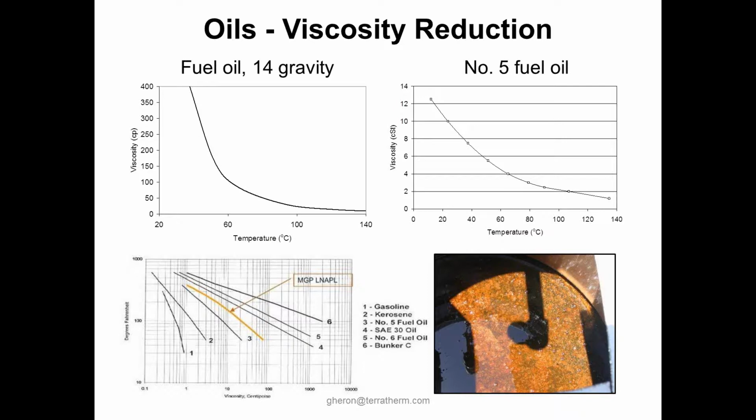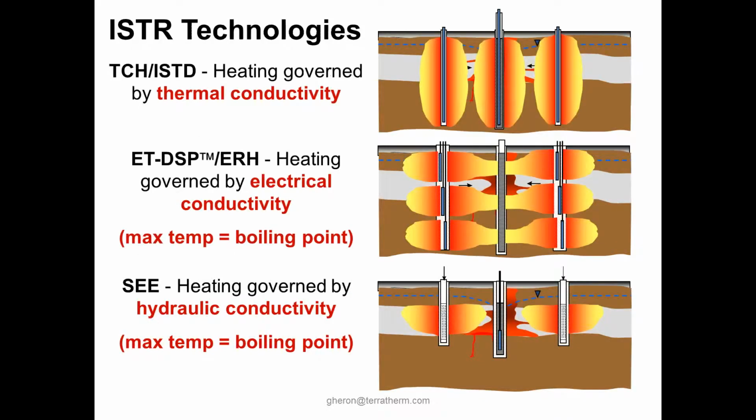But even heavy coal tar, for instance, can start to become relatively low viscosity when it gets hot. And what happens is you do extraction from sites that never really yielded any mass in the NAPL phase, and you start seeing it accumulate in your oil water separator, as you see on the right there. So you can basically start removing oil that wouldn't move before, or you can make oil that moved slowly come out much quicker in the liquid phase as well, not just the vaporization.